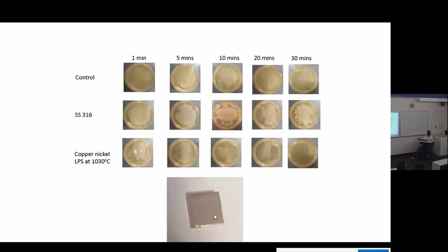So if they need to rethin it, you can just machine them, right? The way that we currently build materials with a 1.6 millimeter layer height, you can turn that down depending on whatever your application is. So that's just our standard build height. And that's mostly because it doesn't really matter for us. We're looking at building industrial sized 3D metal parts. So break it up into smaller pieces just makes it take longer, which in our case is a negative. So it's all about being able to make the part very quickly, hence we do larger layers. We even go up to about 2.7 millimeters for some of our high deposition speeds, but it can be turned down. In our applications, there's no point.